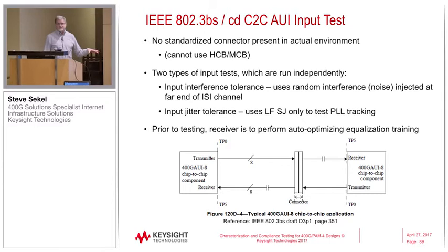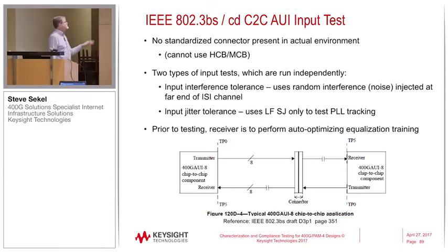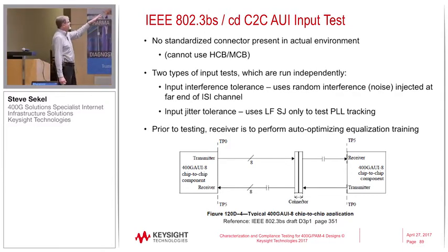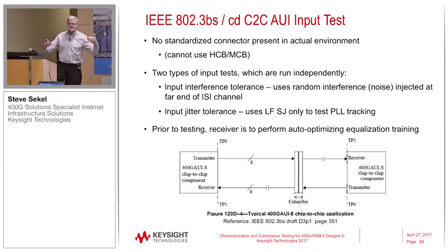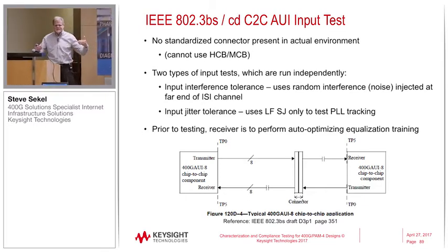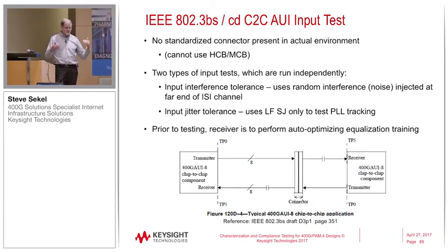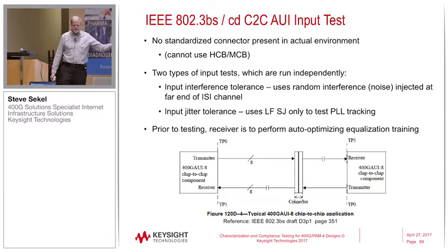Okay, so questions on the aggressor. I'm going to move into the chip-to-chip now. This is, again, covered in 802.3bs. It's about a 25, approximately, everything specified in dB. There's a 10 dB channel, a 20 dB channel, and it assumes that works out to roughly 25 centimeters of electrical length. In the case of IEEE, OIF has different numbers for theirs.